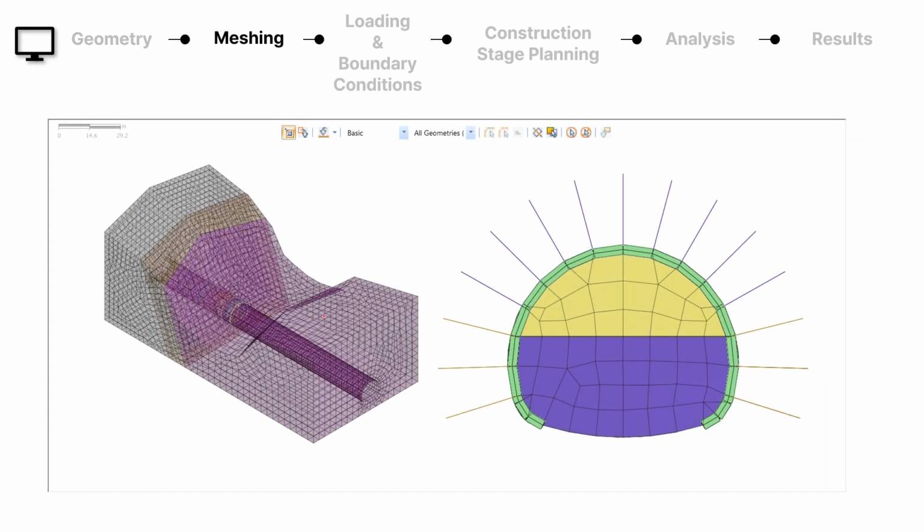And in the second model, so this is your tunnel, and this is where we only have one set of liner. When we are progressing with the tunnel, we just apply the change property option to change the property of the liner from your primary shotcrete to permanent liner. That is possible in the construction stage methodology.